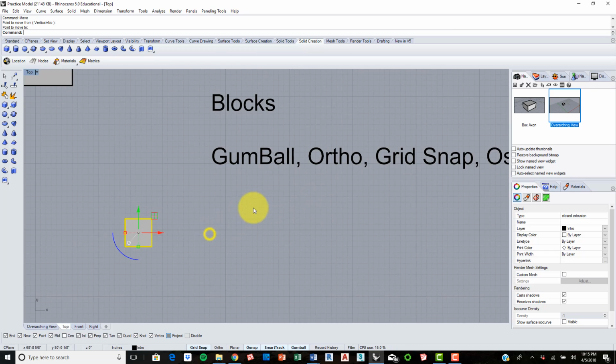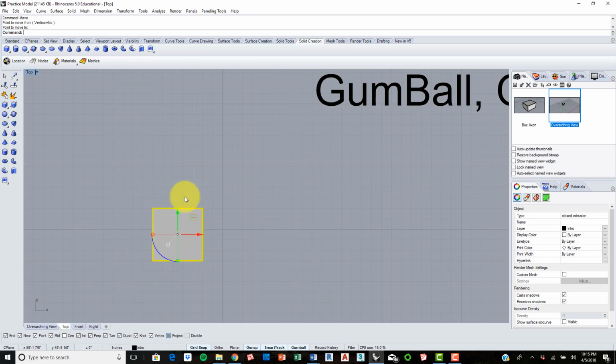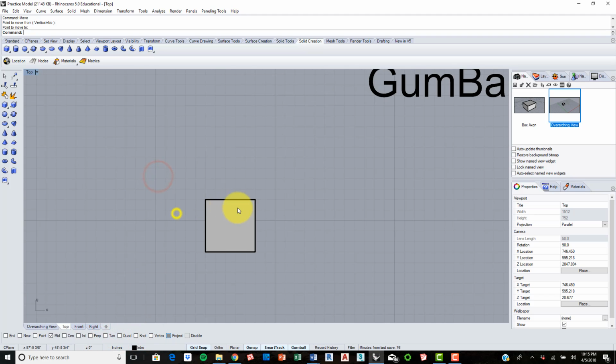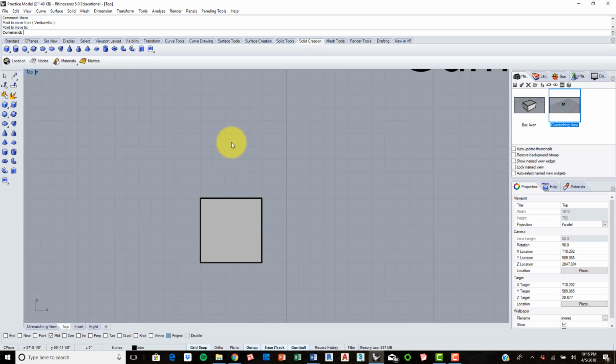And so other options such as snaps will actually give you the ability to choose where you want to snap drawing elements. Down here in the corner, we have these different options for snapping. So essentially, if I go ahead and turn all of these off, and let's say I want to actually draw a line leading off of this box.